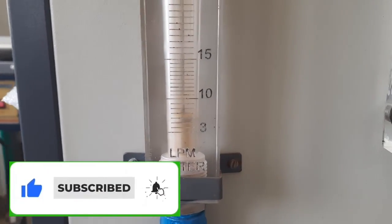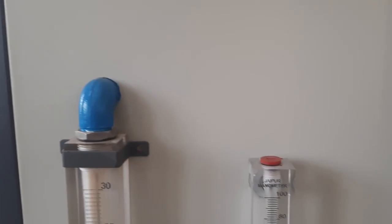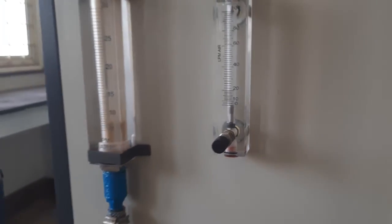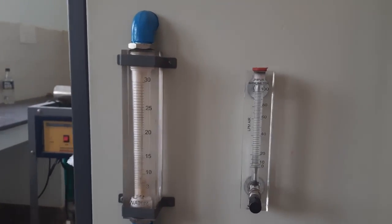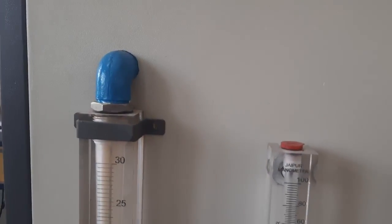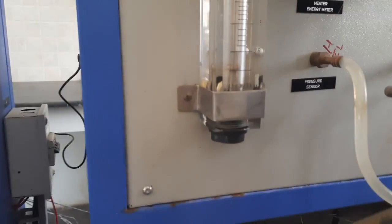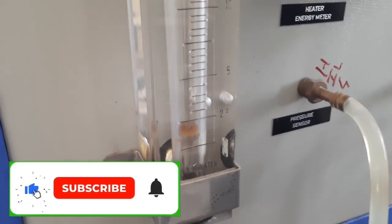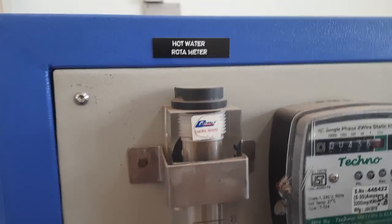One is for water, which will measure the liters per minute of water in 3 to 30 LPM, and for measuring the LPM of air, we have a rotometer attached to it. So that way this rotometer can be used to measure the volumetric flow rate of both liquids as well as gases and gas mixtures. And the principle which we have discussed, I hope it might have given you the understanding that there are only 3 forces acting on the float: the drag force, buoyancy force, and the weight force.